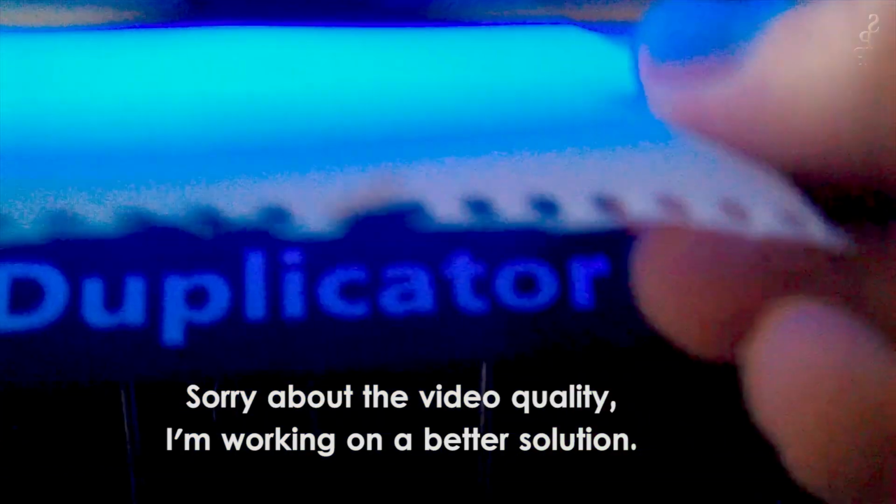Sorry, the camera's jiggling around a lot. I'm obviously trying to do 2 things at once. And then it goes into the middle to just check that, which is the most important place to get right, obviously. Leveling the build plate is quite important. If you don't have it level, you will struggle to get good prints, whether because they don't stick to the build plate properly or they don't extrude properly.